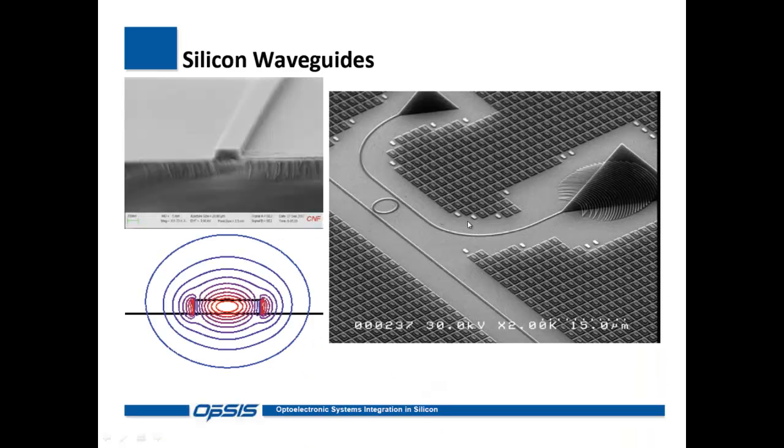If we look a little bit closer at this device, you can see that we're using the silicon waveguide in SOI. There's a ring resonator, a classic device for filtering in silicon photonics. But over here is where you see a grating coupler being used. So grating couplers are not just something of research interest. They're being actively commercialized now.